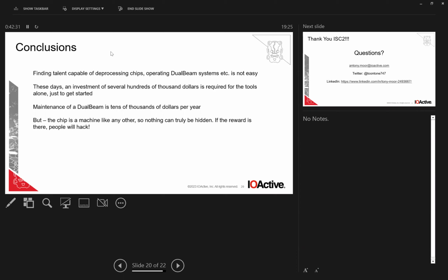The simplest example of that is a NOT. You've got a 1 coming in, you've always got a 0 coming out, or vice versa. Another simple example is a buffer, which just does nothing. It just extends the signal from one place to another. Then you have very, very complicated logic cells, which will take 4 inputs, and the output will depend on the 4 combinations of 1s and 0s going in.